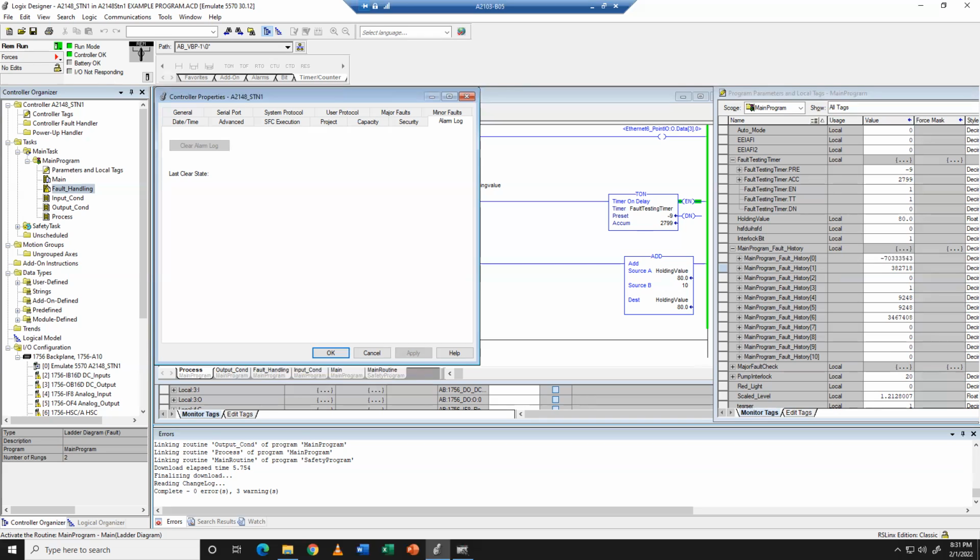Normally open contacts: start buttons, light switches, momentary push buttons, things that you only want to see when they turn on. Pump overloads, as long as you're not looking to use the overload status inside another circuit. For PLC statuses, those are your normally open contacts.